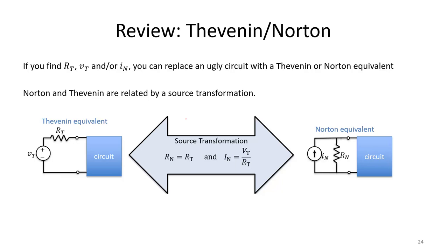Also very important, please remember that our Thevenin and Norton theorems are related by a source transformation. So if you've found the Thevenin equivalent, you can use a source transformation to find your Norton equivalent.